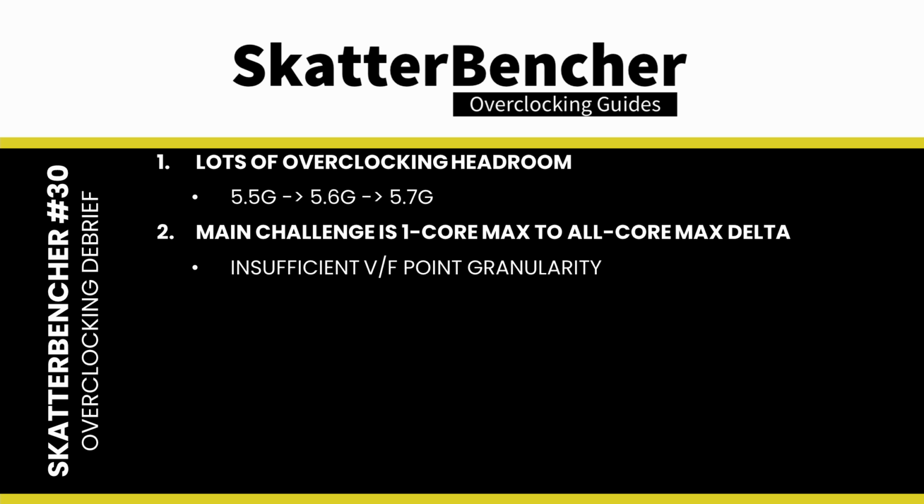The lack of control is annoying, as it's really important to fine-tune the voltage in an all-core workload to manage the temperatures. Speaking of temperatures, as you can see from the Prime 95 results, even at default settings, there's not much thermal headroom to push the all-core frequency. When unlocking the Turbo Boost 2.0 limits, we already hit 100 degrees Celsius in an all-core AVX2 workload as the CPU package power hits 300 watts.